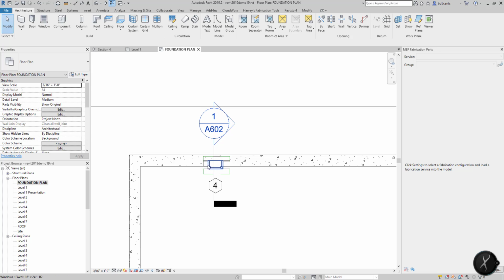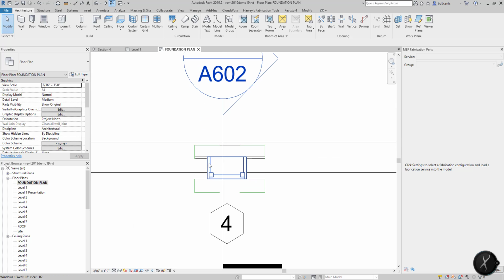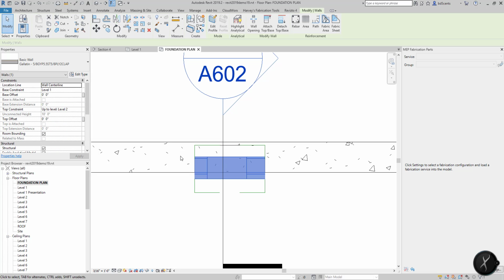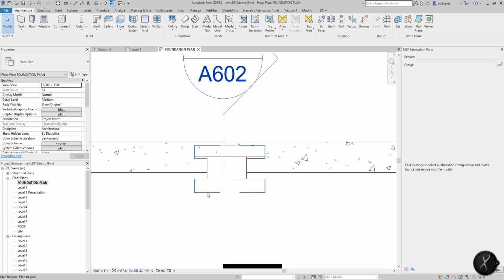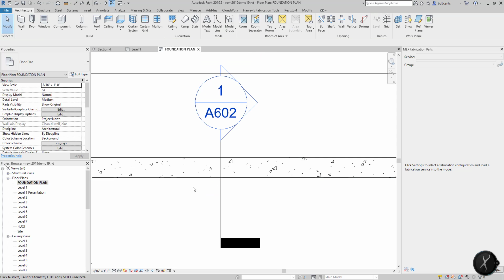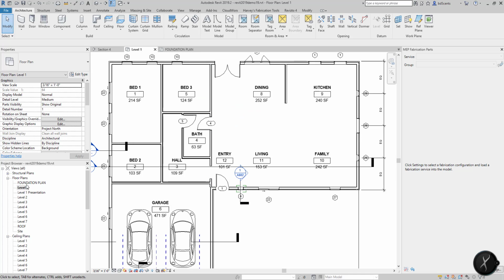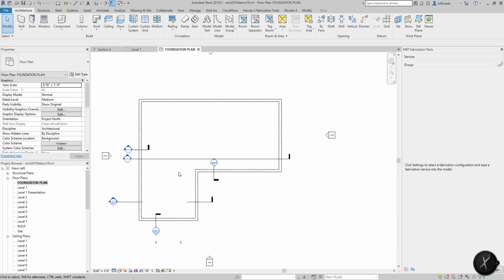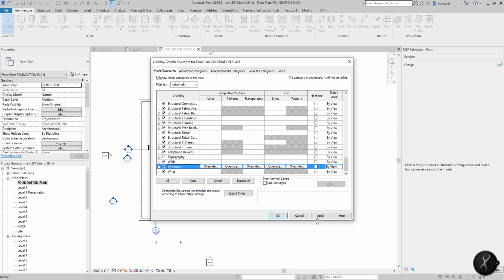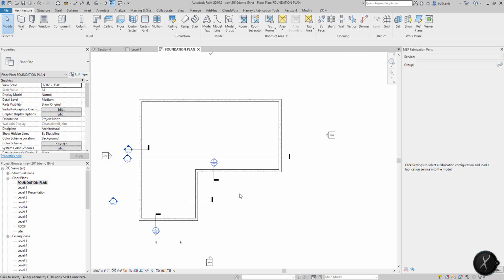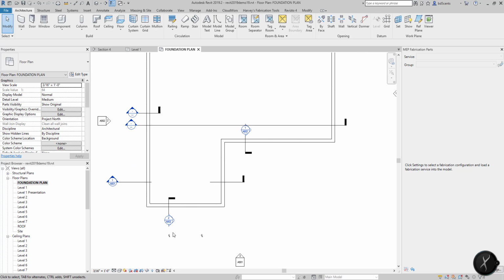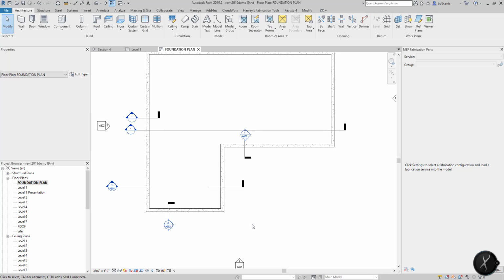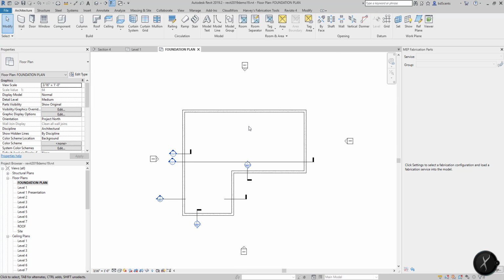Now, we don't want to see windows in this view or plan regions. So what we're going to do is VH the windows and VH this, actually we'll VH this plan view. We can delete it actually entirely. It duplicated it on this new view. So I just went ahead and deleted it. I did hide windows, I believe, so I'll go ahead and turn those back on even though we won't be seeing them. But just to check to make sure that's in good shape. I can also delete these center lines, so I'm just kind of tidying up the view.